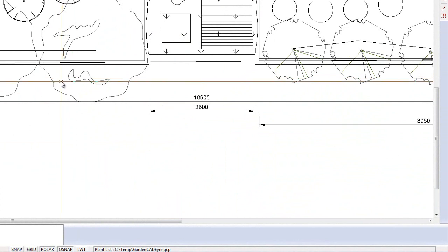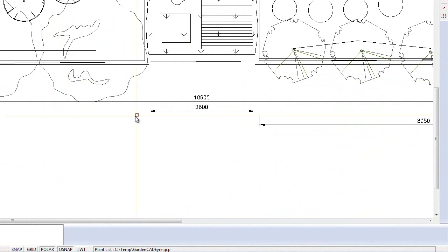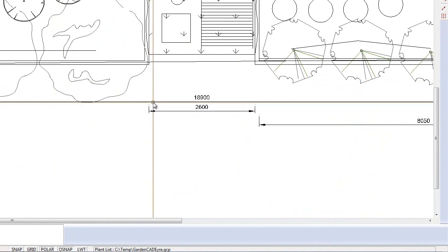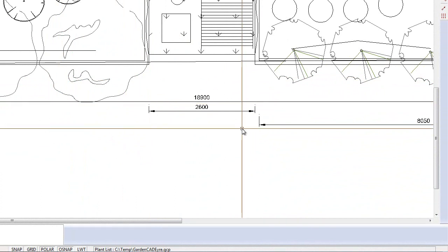So that's the best way to handle drawings with dimensioning. If you explode the whole block at this stage, you'll find that the dimensions will destroy themselves, and you'll need a new dimensioning style and have to work hard in this environment. It's far better just to remake the block if you need to make some changes here.